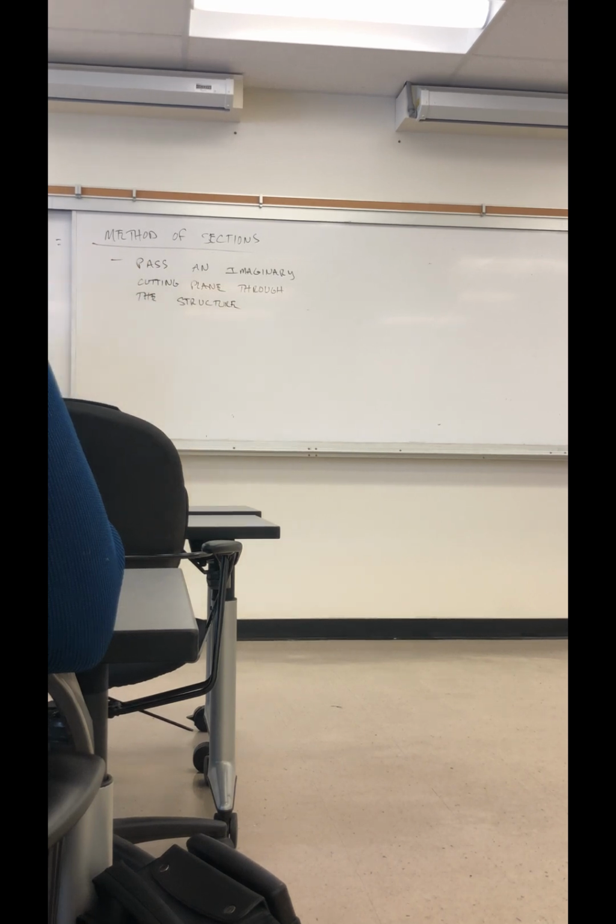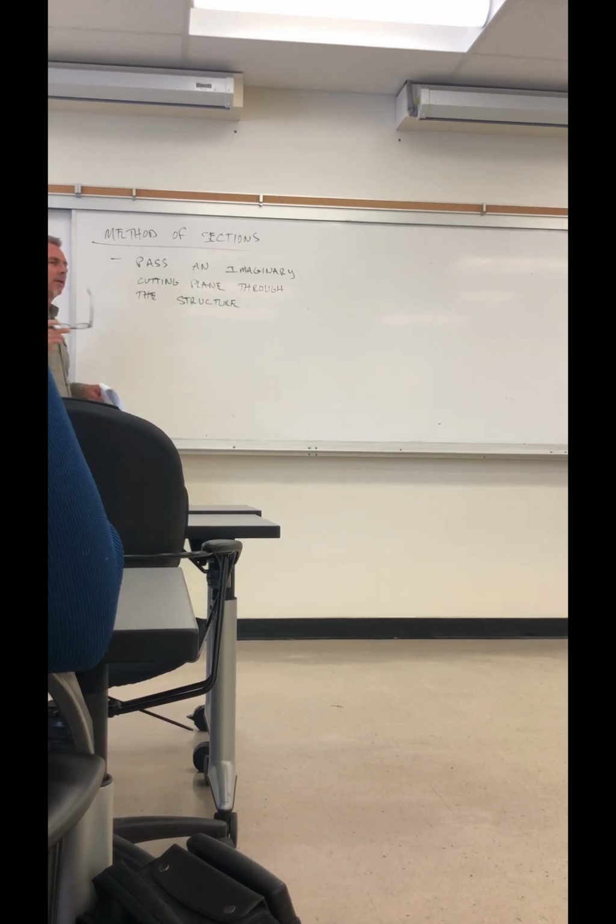So we're going to pass an imaginary cutting plane right through the structure, all the way through. But you have to, and this is important, you have to cut through the members that you want to solve for the forces. You can't cut through the structure and then not have cut through the member that you're trying to solve the force for. You won't get that result.